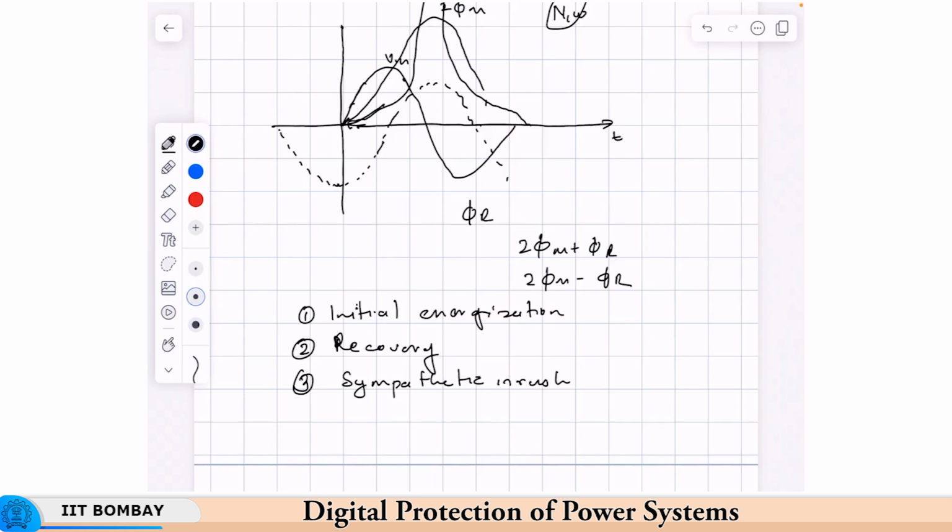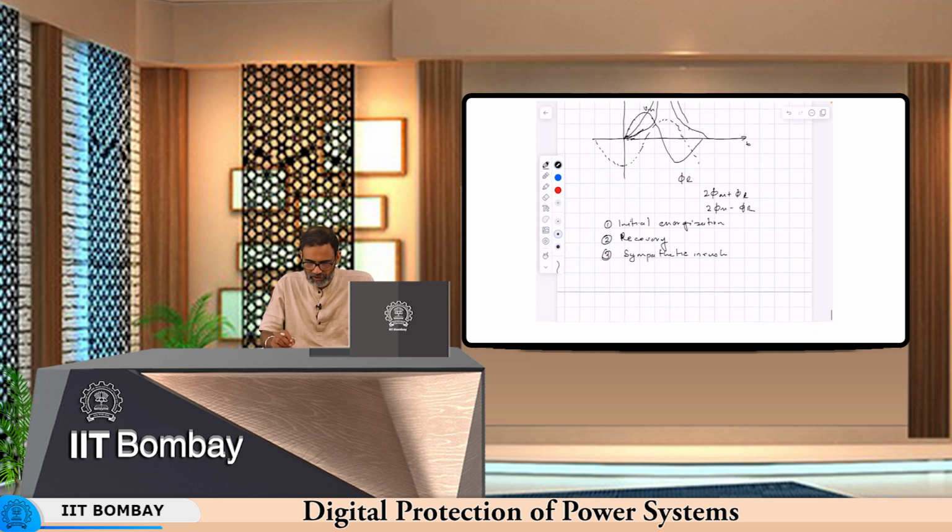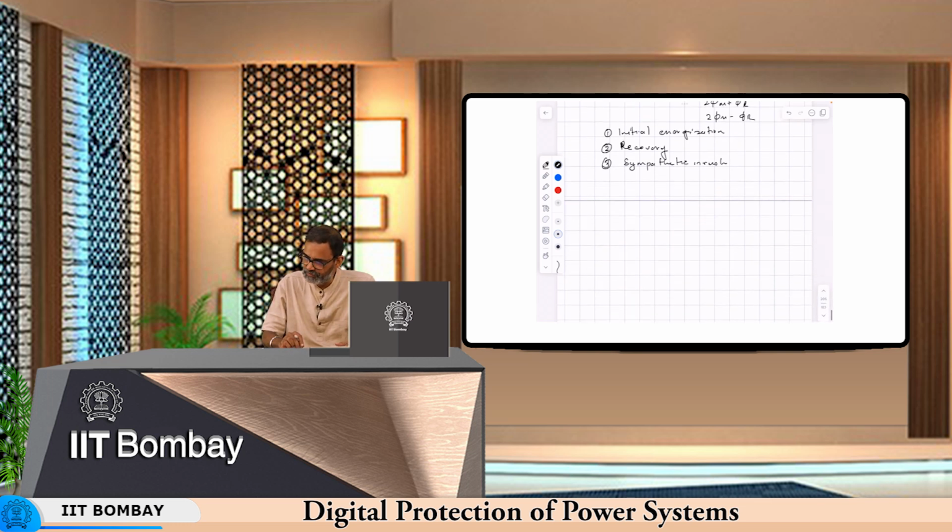This usually happens when a parallel transformer is energized. So the inrush there will cause a similar inrush here. It is known as a sympathetic inrush. We are not going into details of all this. As protection engineers, we are not studying this inrush phenomenon here, but we should be aware of what the kinds of inrush are and what kind of restraint is provided.